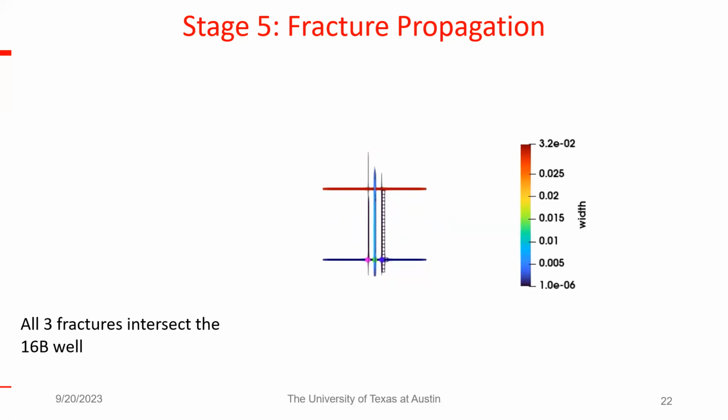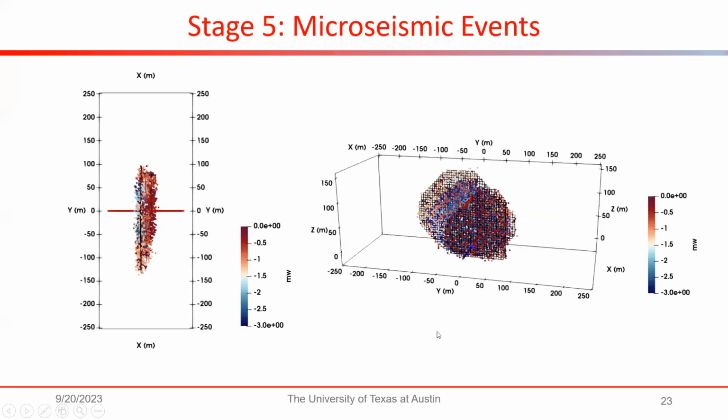we can implement in the 16A well, but it would be hard to implement in the 16A well without any sliding sleeves. So this is something that we would definitely recommend if it's possible, but would be difficult to do in practice in this particular well. But it does offer some clear advantages in the way the fractures would connect the two wells.